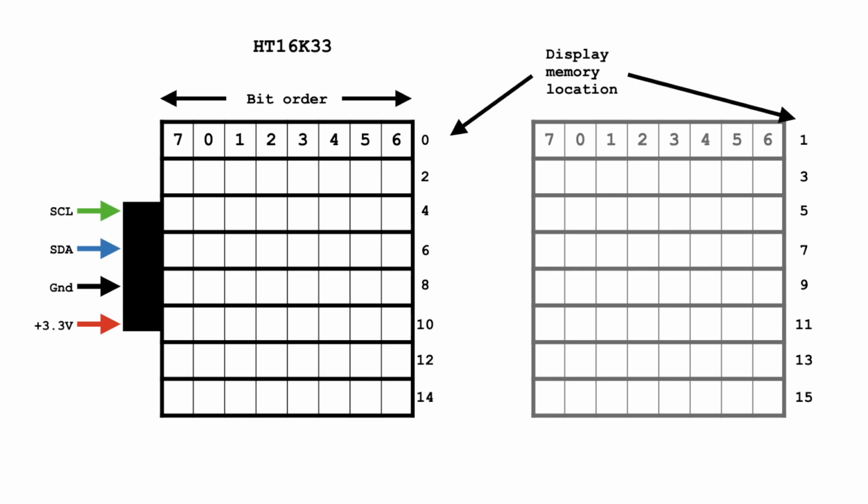In this scenario, each line going across is represented by 1 byte. That's friendly enough, but the bits aren't quite in an easy order. As we can see, the most significant bit has been rotated 1 bit position, and the order of the bits seems reversed from what we would normally like to see. We can also see that the memory location for each byte goes up 2 at a time, so that our first display that we're looking at always has an even memory address, not an odd memory address. We need to allow for this when we send data to the device.